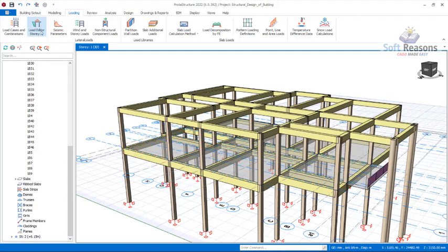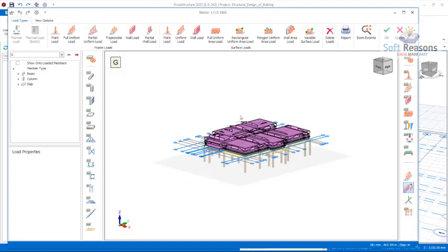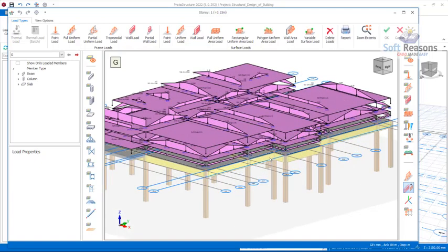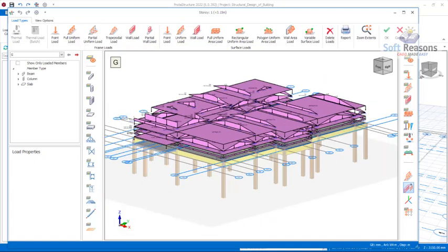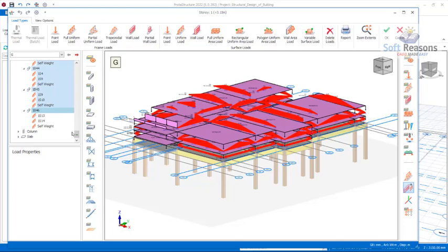So you click on the load editor. So this will take us here. So in these provisions, you can see these loads are the reinforced concrete slab load, but you can expand this beam. All right, get this beam expanded, select the first beam, and then you can come all the way down to make sure you select the last beam to get all of that selected.